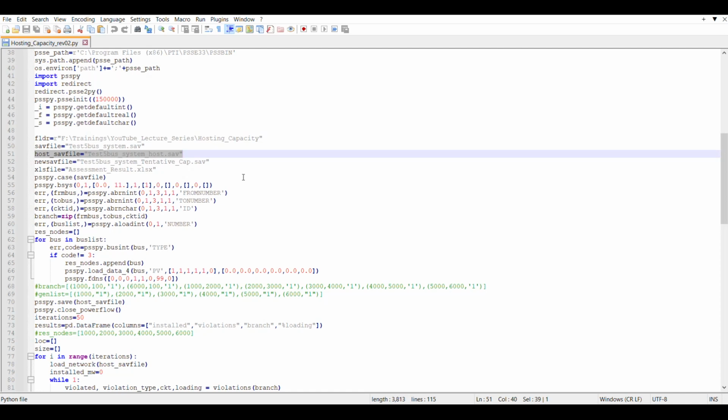It can be done in two different ways. If you are using version 35, within version 35 there is a separate section within the load where you can add DER generation. But if you are using version 33, in that case you do not have it. So now you have two ways to do it. Either you create a mechanism where you subtract your load from this generation and build on it, or you can simply create new negative loads on each node and then add this new generation into it. So this is what I have done.